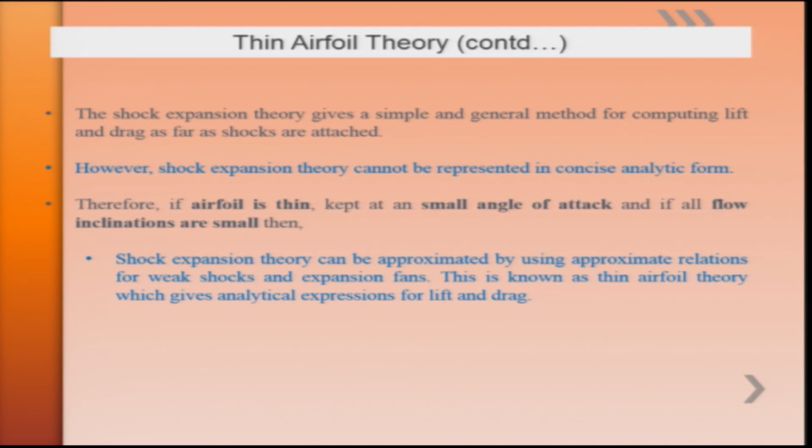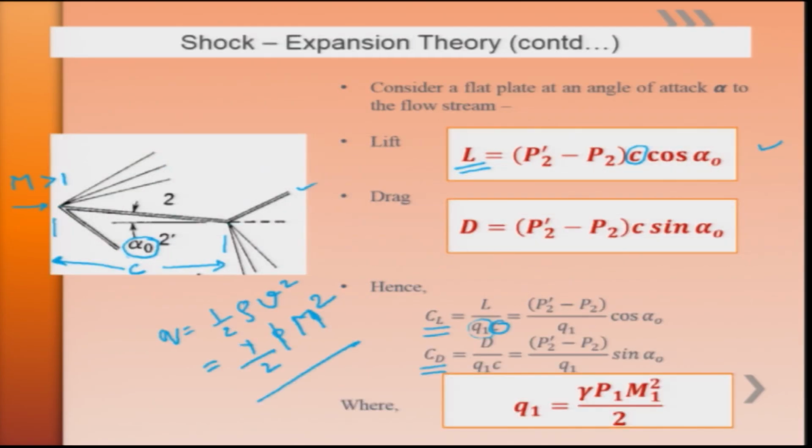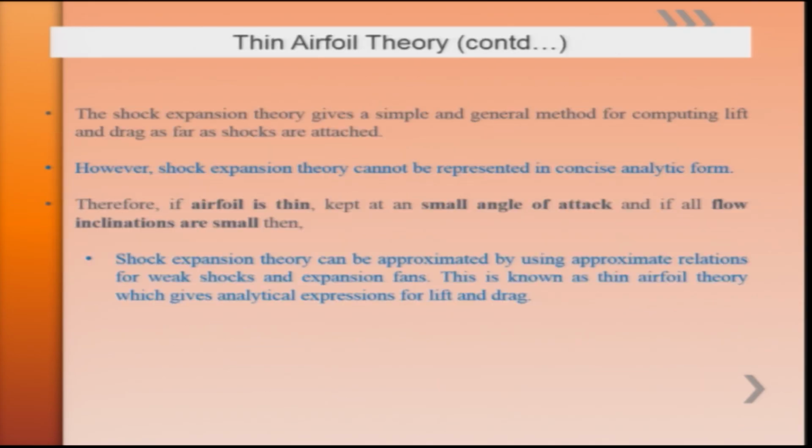Therefore, what we find is that this shock expansion theory, in a very simple flat plate application, can give approximate relationships for CL and CD. However, a closed analytical form cannot be obtained using shock expansion theory for a particular case.